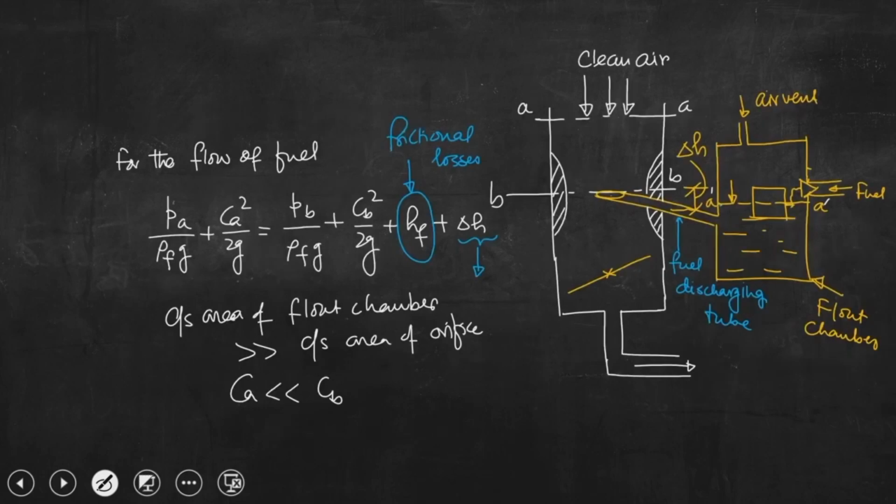Because if we go back to the schematic depiction, we can see that fuel will flow through a tube or a flow path which is very small. So, when the length scale of the fluidic pathway is reduced, the surface tension force will be an important force to be considered in the analysis, but we did not consider that.